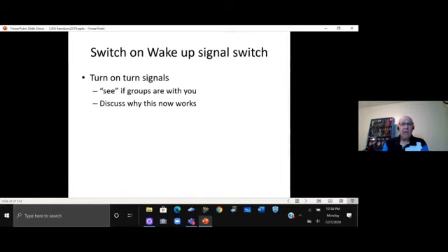It's really tough to do. But here's what I do. I start at the modules. Power, ground, signal, signal. Trace those. 4 modules. DLC, power, power, ground, signal. Okay? Turn on a power supply. Do we have power at the DLC? Do we have everything else? And then work it from there. But a lot of times, all it takes is to have 1 wire or 2 wires out of place, and, you know, it doesn't work.